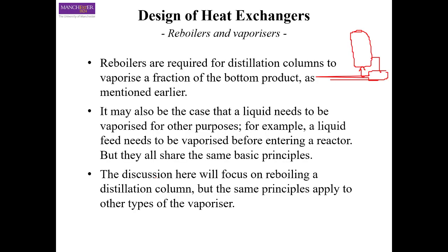So as I said before, reboilers and condensers are very important, especially for distillation columns. So wherever you have a distillation column, you must have a reboiler and a condenser. And these reboilers are very important because when you apply it with a distillation column, the liquid from the distillation column enters the reboiler and it vaporizes the liquid, and then by doing that, it maintains a certain vapor fraction inside the distillation column. Okay. You can have also other applications of reboilers based on the same principle.